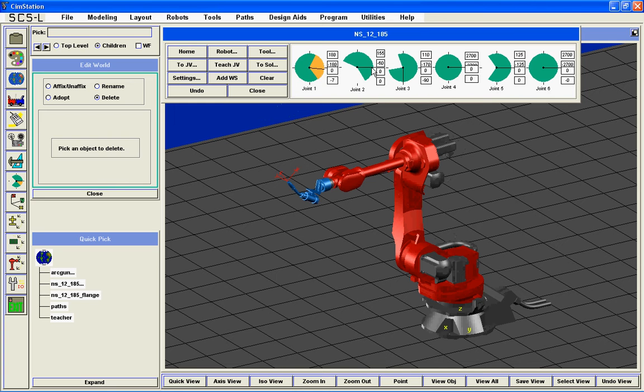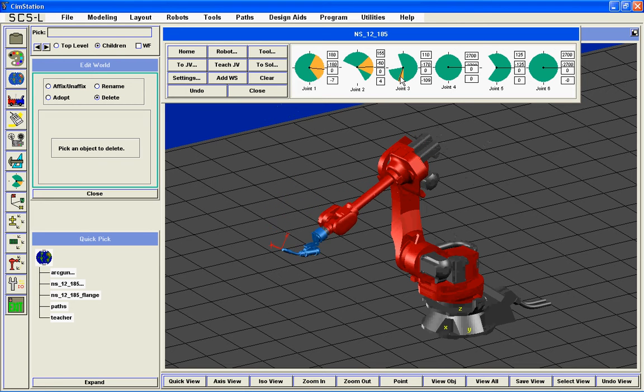it moves joint 1, and you can see joint 2 can be moved, and you'll notice that the joint boundaries, the joint limits, are shown also. If you get close to a limit, that green area will turn red to show that it's close to a limit. The yellow is showing how far the joints moved for that particular movement, and if you press clear you can clear those. We'll see that.